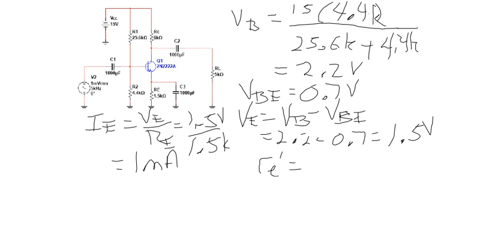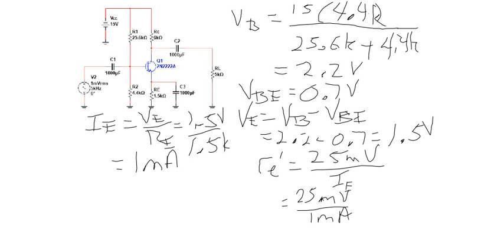But our book uses 25 millivolts, and that's what I've always used, and it works out fine. 25 millivolts over 1 milliamp, or 25 ohms.